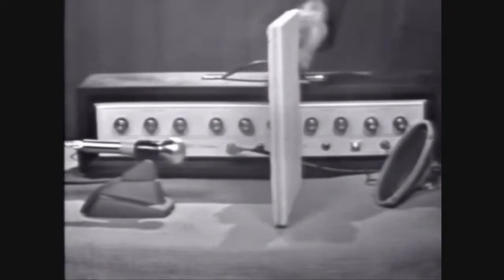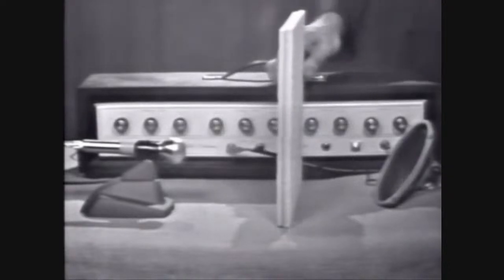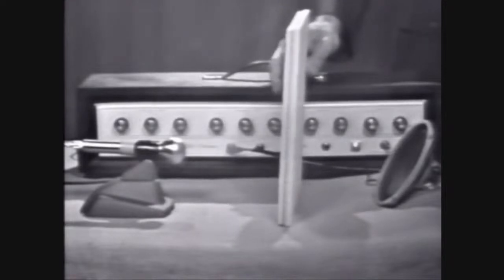The squeal builds from a relatively low level to a very high level. And if allowed to continue, very high oscillating currents are built up that may damage circuit components. For this reason, the amount of feedback must be controlled in an oscillator. The correct amount is just enough to overcome the losses in the circuit. Any amplifier will oscillate if feedback occurs.